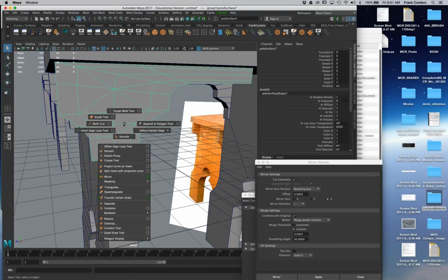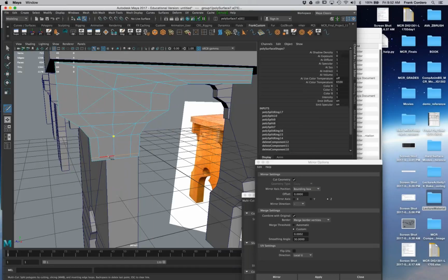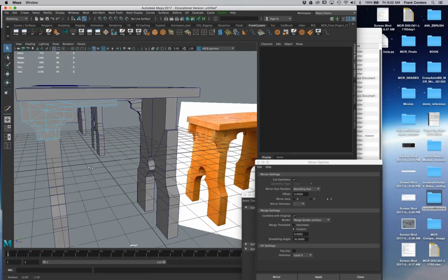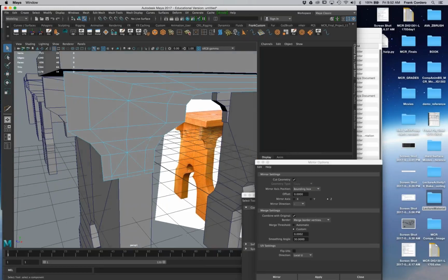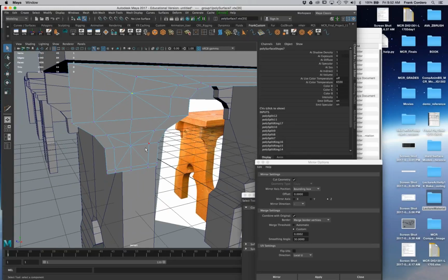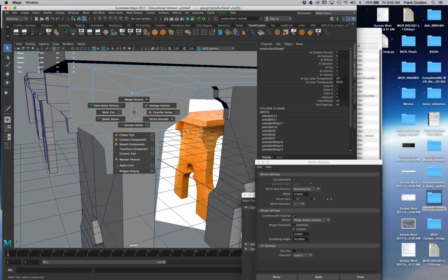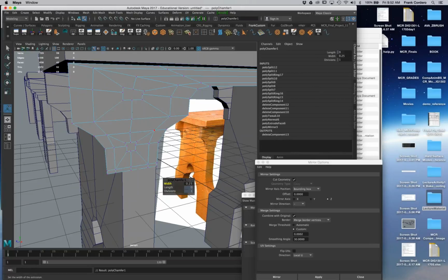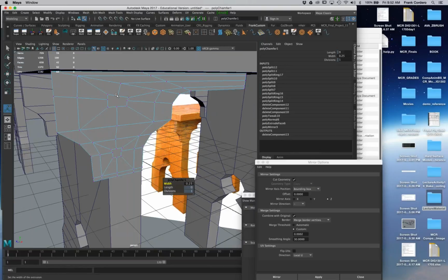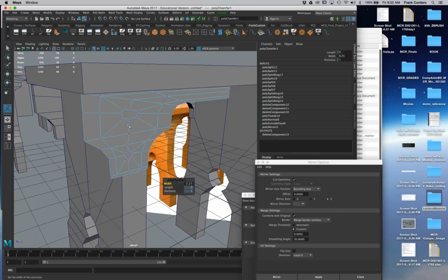Now I'm going to make the rest of the X over here and over here. So, X marks the spot. That's an important thing because it's going to set you up. You're saying, what's the big deal about the X? Well, you can turn a vertex where the X marks the spot into an 8-sided face. The way you do that is you select the verts and choose chamfer vertex. You see that? Chamfer vertex gives me the opportunity to turn a vert into 8 faces. Well, now I have to shape this.